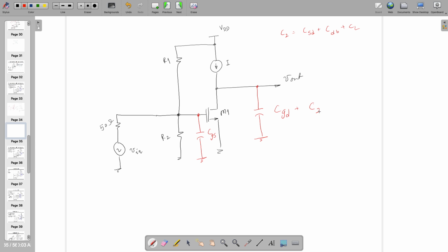So effectively there are two capacitors. So in this system there will be two poles, right? Two capacitors means two poles. Let's find out where the locations are. So the locations are as follows. You need to replace each of the capacitors with a known Thevenin voltage, and you need to find out what is the available resistance at these two nodes, right?